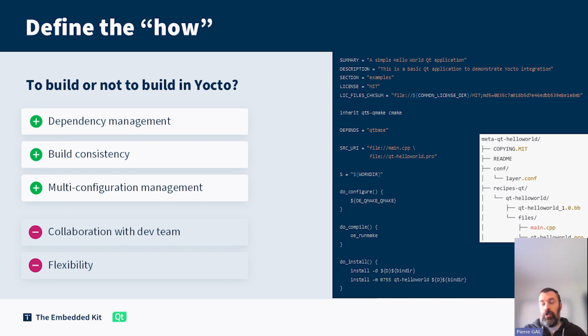And today we will focus on Yocto, because in this embedded world, we at the Embedded Kit, but a lot of partners and companies in this world really trust Yocto for building this operating system. Why Yocto? In two words, just because of the level of customization you can bring to your operating system. And limiting the number of components, optimizing the system is really a key topic for optimization purposes, but also for cybersecurity purposes. That's not the meaning of today's conference, and there are a lot of other conferences about cybersecurity, but least privilege, minimal image, reducing the attack surface is really a key topic.